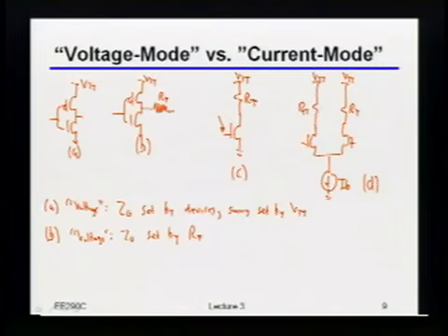So most of the drivers that you see that look like this, that's actually what they intended to do. Okay, so that means that the devices themselves, those would have to have very low impedance. And so that's why those look more like, let's say, a voltage mode driver. So Eric, like I said, I understand where you got to your current mode because I could have actually done it in a different way, but usually that's what they actually mean. Okay, now how about the other parameter? What else is going on with this one? Which is probably the more direct way to say that it's a quote-unquote voltage mode driver. Swing is set by supply. Yeah, the swing is set by the supply, right?